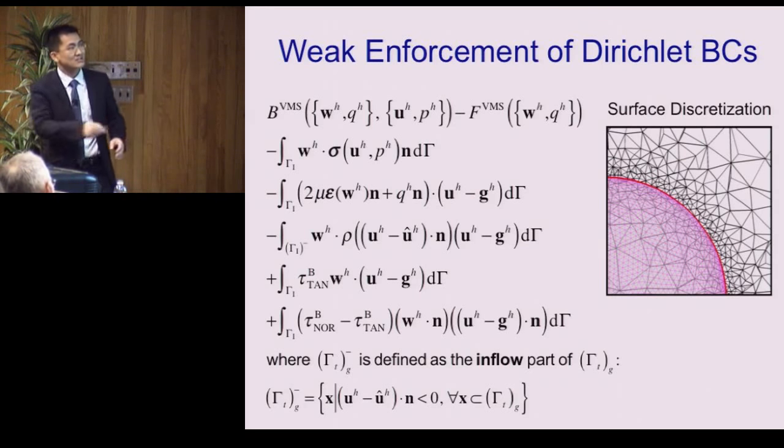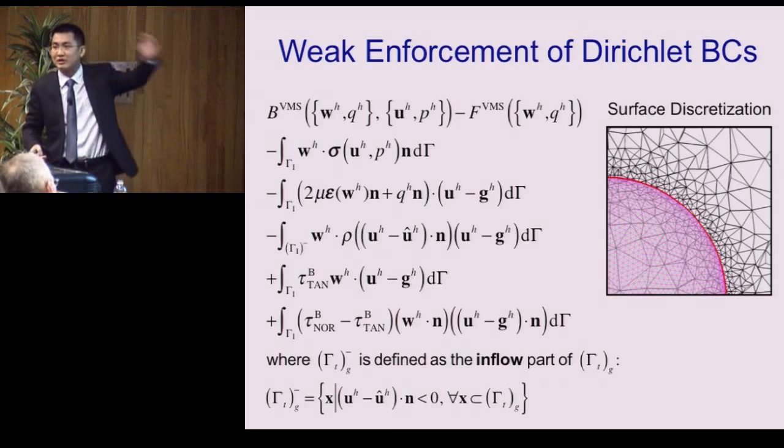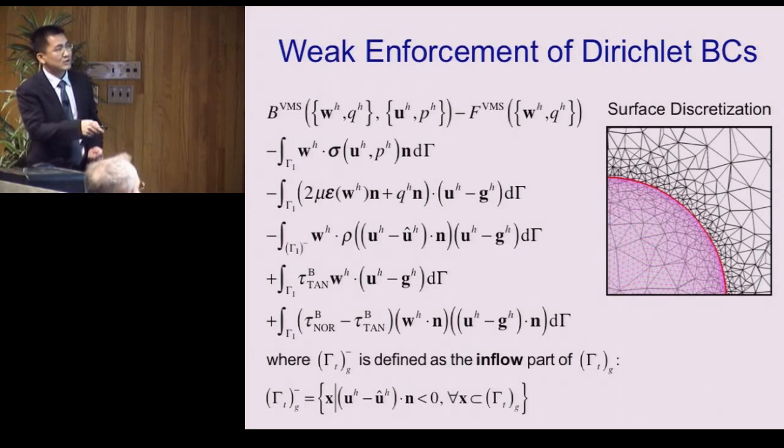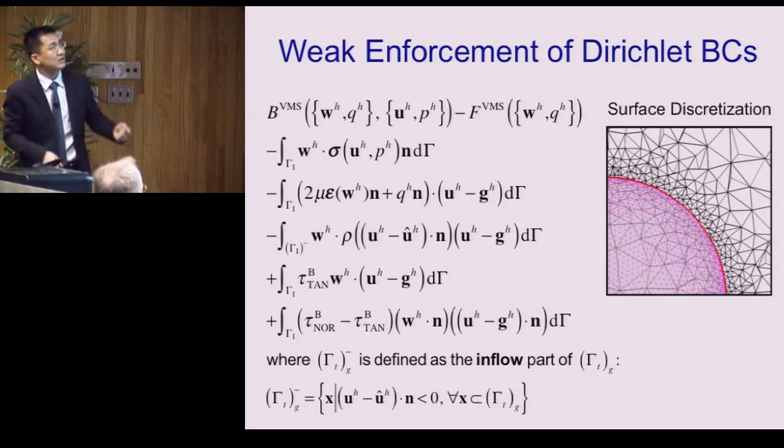So basically, if you have a surface discretization, I can integrate over that to enforce some kind of constraint. Then we said, well, why don't we just match the surface? They don't match, that's fine. But we just integrate over the surface using exactly this weak enforcement of Dirichlet boundary condition formulation, weak BC, and